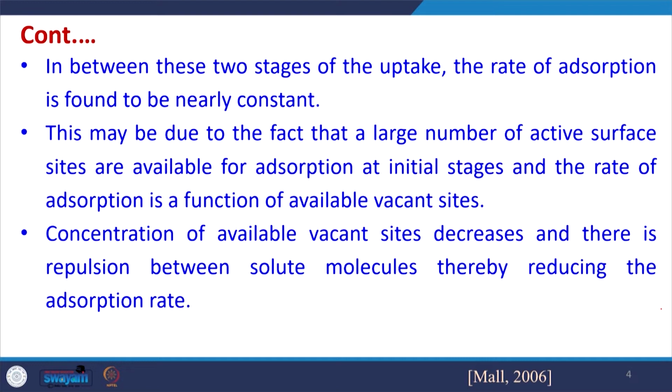Now, initially there will be a large number of active surface sites available for adsorption. That is why the rate of adsorption will be high, and it will be a factor of two things: the concentration of adsorbate in the solution and how much adsorbate is already present on the adsorbent.